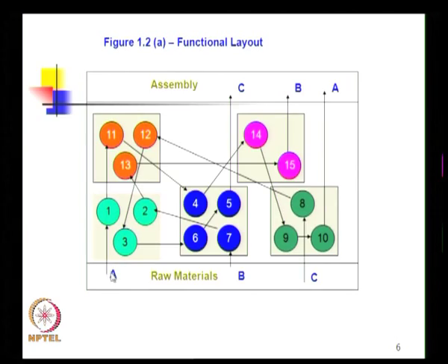So, in line layout, it is always possible to have better quality and fewer changeovers, as machines that are required to make the product are now located close to each other. Here, machines that are required to make A are spread out. So, there is more control in a line layout than in a functional layout in terms of control of the product. So, now practitioners and researchers thought, can we apply some ideas from the line layout into batch manufacturing, and cellular manufacturing was born through this.